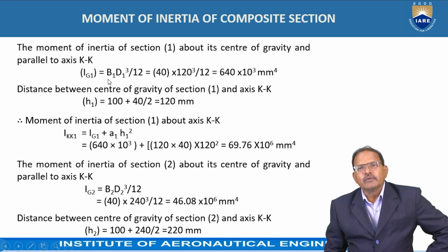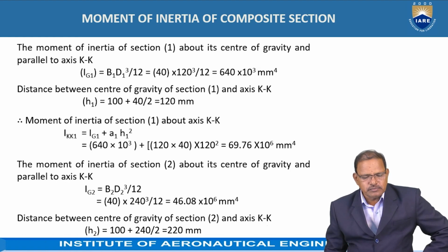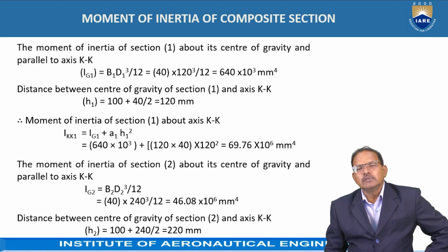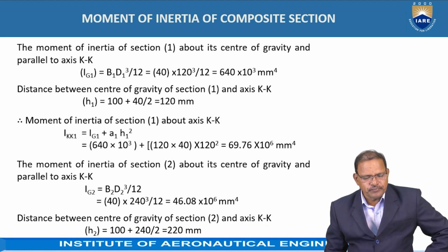After dividing, identify the reference axes. One is a horizontal axis, which should pass through the bottom of the section, and the vertical axis always passes through the extreme left of the figure and perpendicular to the x-axis.